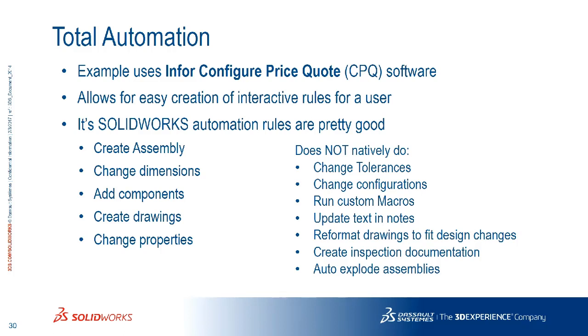and I can pull in that info. One other way you could do that is if you start the macro recorder and you click on a dimension or a drawing view and hit stop, and you go into the code that it created, it'll tell you exactly what the dimension is. And you can pull it up that way.